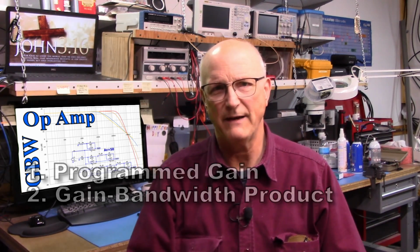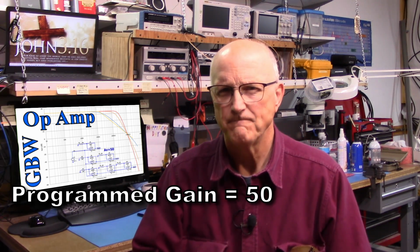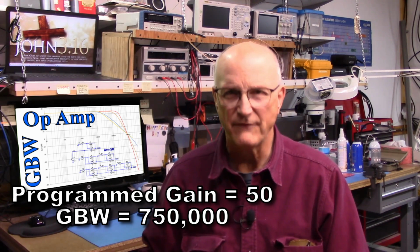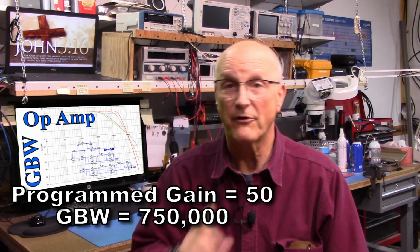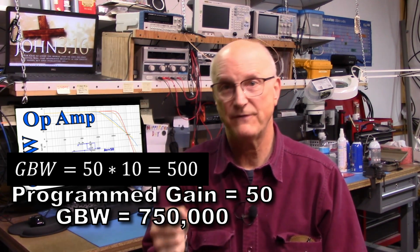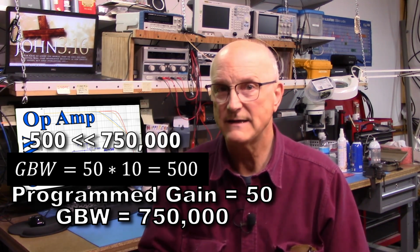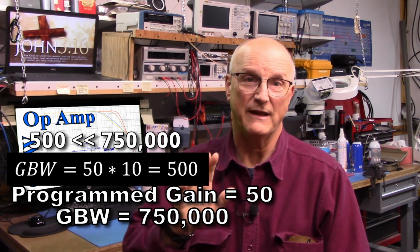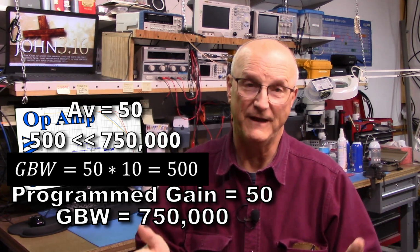So let's go to our example. We have a programmed gain of 50. We also have a gain bandwidth product of 750,000. So at 10 Hertz, the product of the programmed gain and the frequency is 10 times 50, that's 500. 500 does not exceed the gain bandwidth product of 750,000, so the gain of the amplifier is going to be, as programmed, 50.